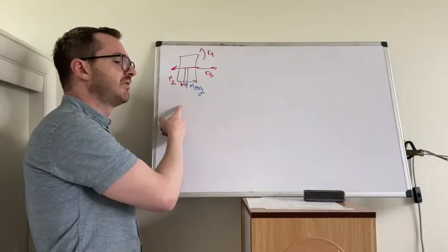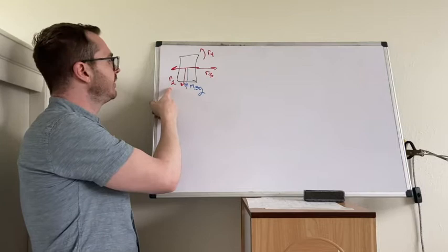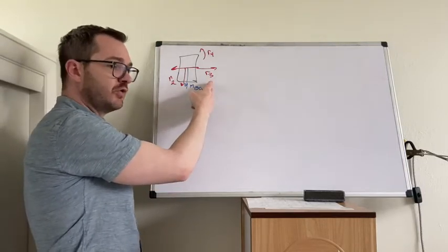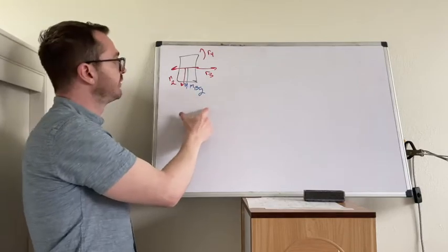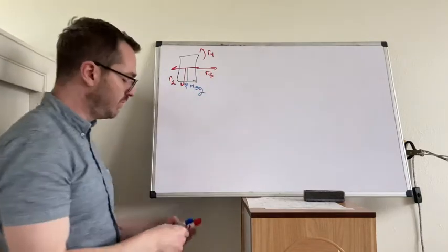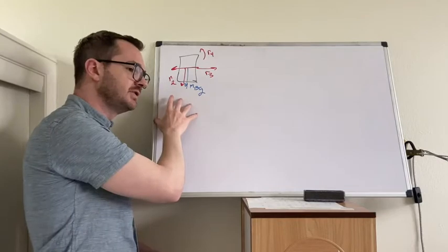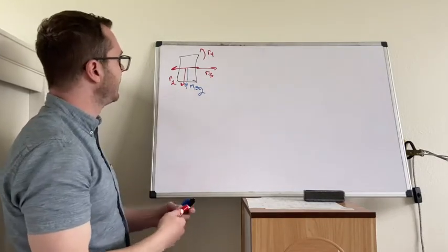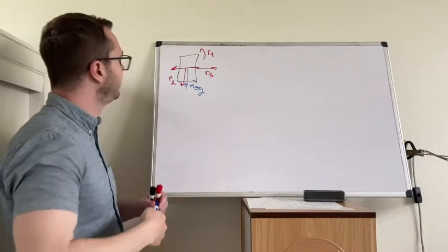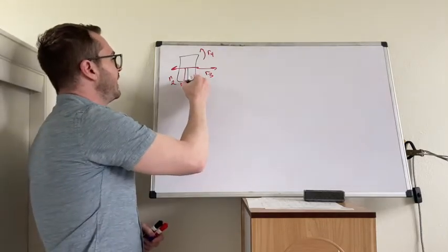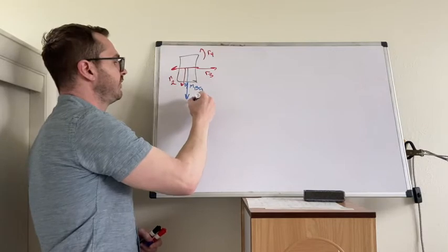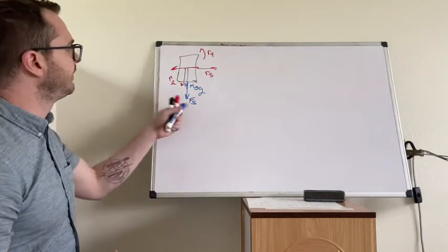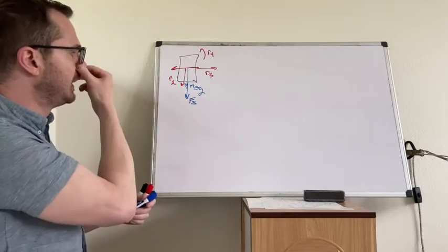Here's the free body diagram for B. Remember, there's gravity. R2 is negative, it was positive on body A. R3 is the normal force that keeps the block in the groove. R4 is the reaction moment that maintains the orientation of the sliding block with respect to the slotted rod. And also, let's not forget, there is also a spring force. I'm going to call that Fs. So we have all these on the free body diagram.